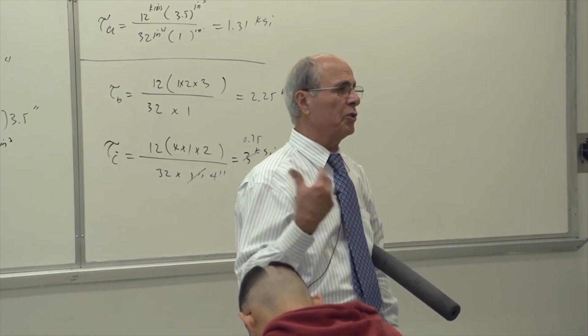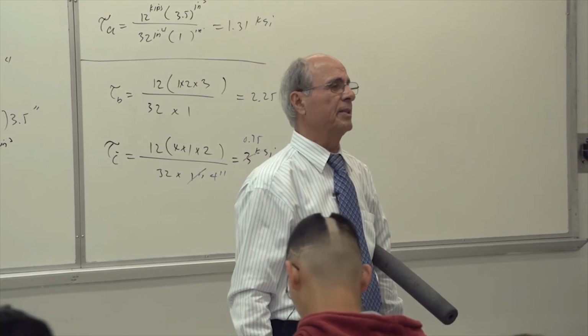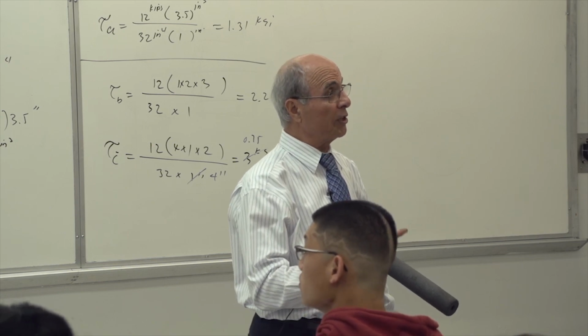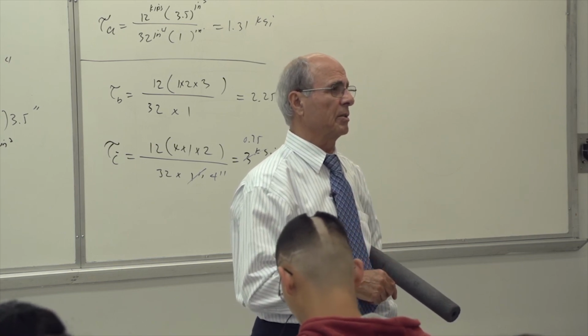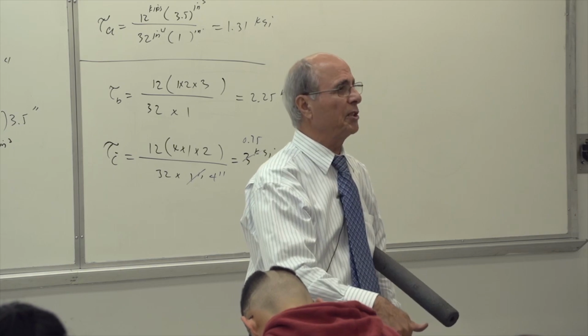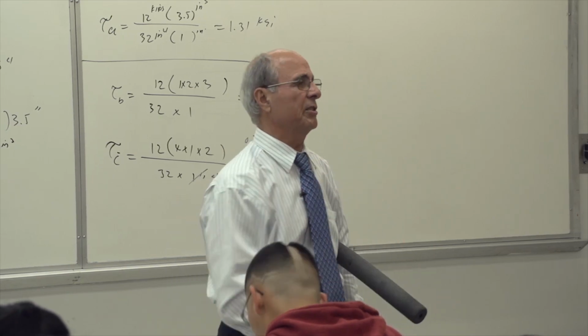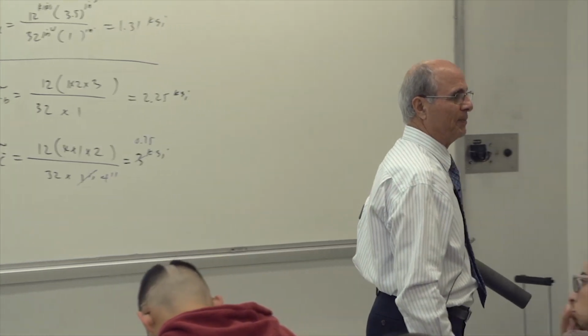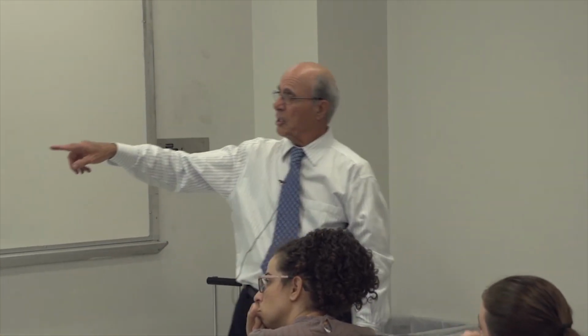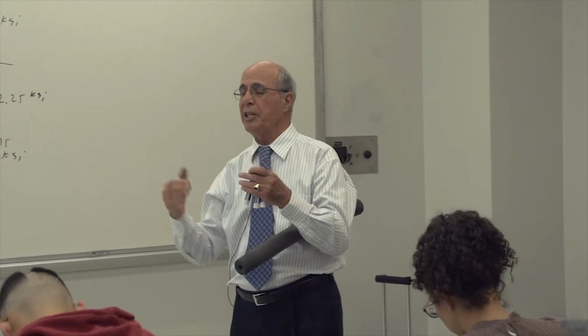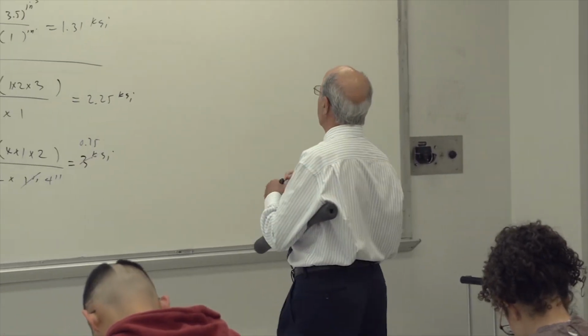Why do you think this is different? Why should it be different? Because you are thinking of the shear force, which was positive. The positive shear force actually gives you a negative shear stress, if that's what you want to do. Yes? Okay. And this sign convention for compression, I already assigned for the sigma.